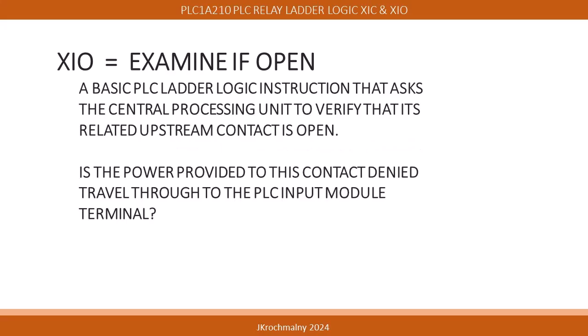The next set of PLC relay ladder logic to understand is the XIO, or Examine If Open, instructions. The Examine If Open instruction is a basic PLC ladder logic instruction that asks the central processing unit to verify that its related upstream contact is open. Is the power provided to this contact denied travel through to the PLC input module?